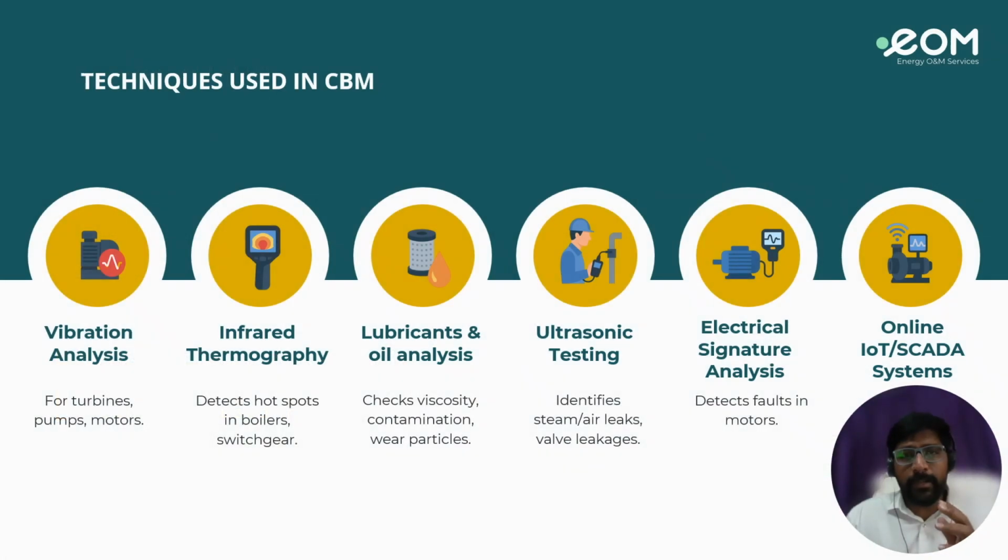To implement condition based maintenance effectively, modern power plants employ a suite of technologies. Those are vibration analysis, which helps in detecting imbalance, misalignments, bearing wear, or mechanical looseness in rotary machineries like pumps, turbines, and other motors, providing early warnings before catastrophic breakdown occurs. And the next one is thermography infrared scanning, which identifies hotspots in electrical panels, transformers, boilers, or rotating equipment, and it helps in preventing fire hazards and energy losses as well.